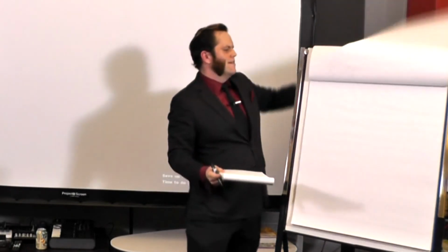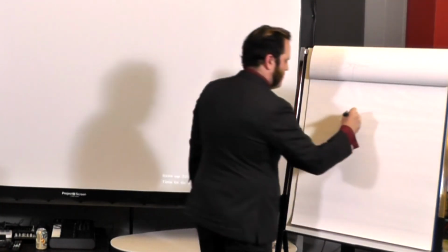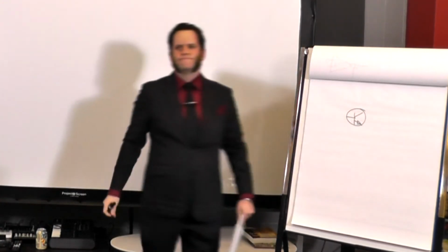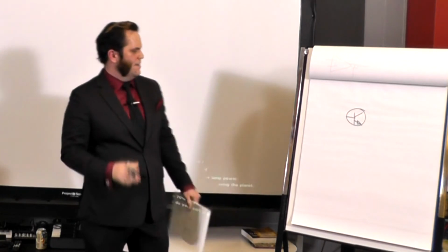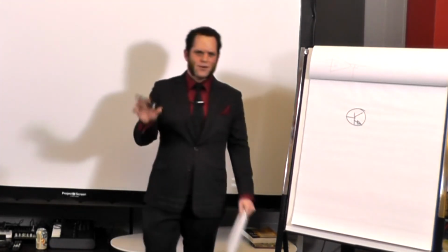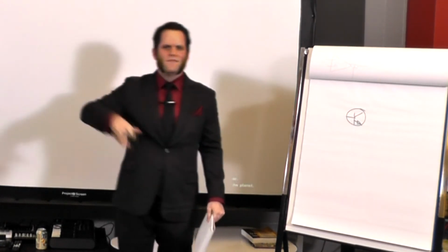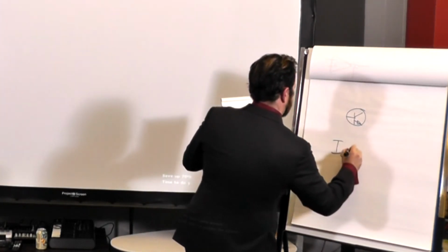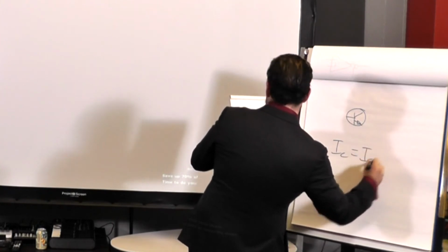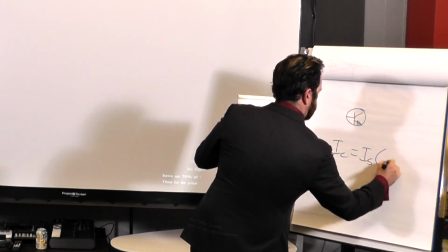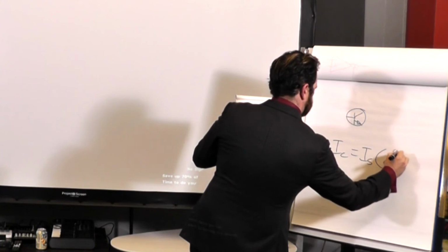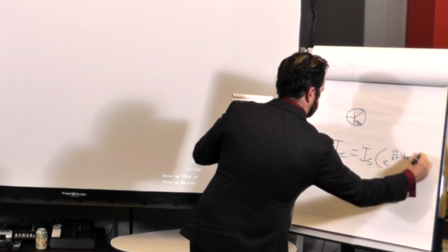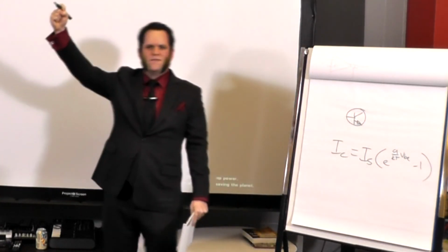It turns out we've got some really neat devices that do this for us, one of which is called a BJT. And I'm not talking about the small signal model here. We're going to the Ebers-Moll device physics intensity. I wrote the thing down here. Collector current is equal to reverse saturation current times e to the some constant stuff times your VBE, and then there's a minus one. Woo! Yeah, device physics.